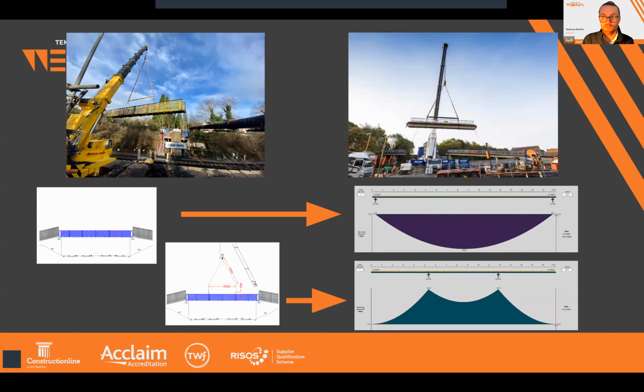And that stress distribution in the cross section is going to be totally reversed, putting the top half in tension and the bottom in compression, which is really important to understand in terms of what materials are being used in that structure, as well as if it's seen that force before, because we don't know what the connection details are, for example. So this is especially important when we've got materials such as cast iron, which have very different tension and compression capacities, and the restraint conditions on the flanges may well be different as well between the top and the bottom.